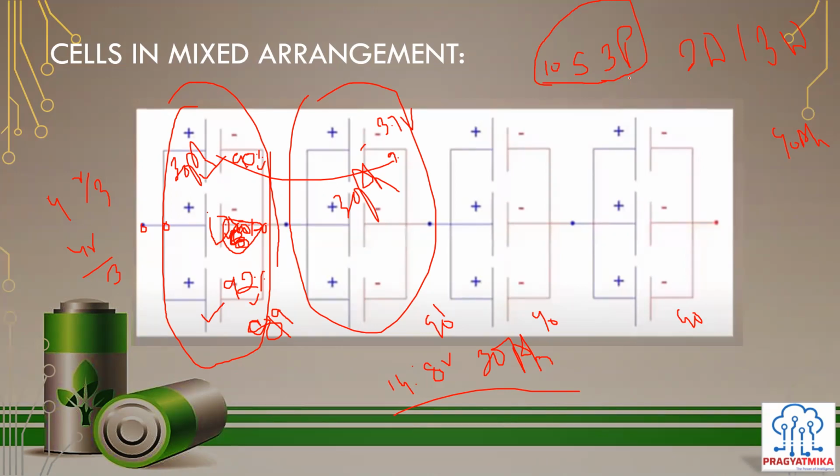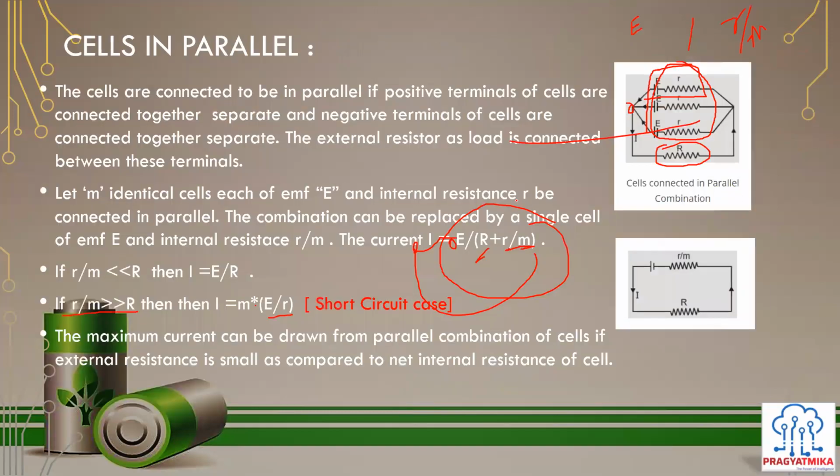So that's why, as a normal battery pack, you will see the parallel-oriented connection, and BMSs of like 10S, 12S, 14S, such kind are there. And in this, the problem will always remain that if in the parallel combination one cell has gone below, you will not be able to observe which one.